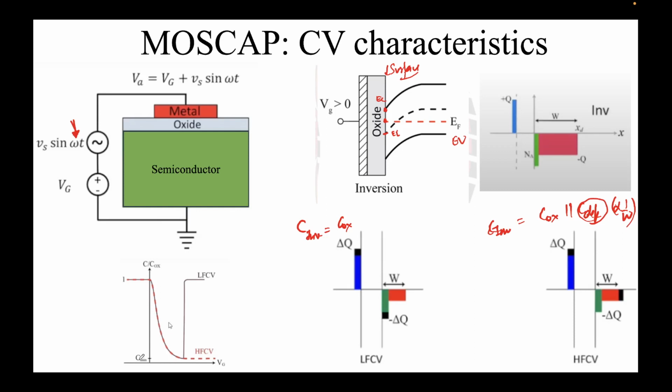So in this problem: in a typical MOS capacitor, high frequency capacitance is less than low frequency capacitance in which regions of operation? We had just talked about this. So this is C versus V. I'm going to draw that again. This was the accumulation region. I'm talking about an NMOS here. So let me first draw this. This is your metal or gate, and you have your oxide here, and you have your semiconductor here, let's say P type, grounded.